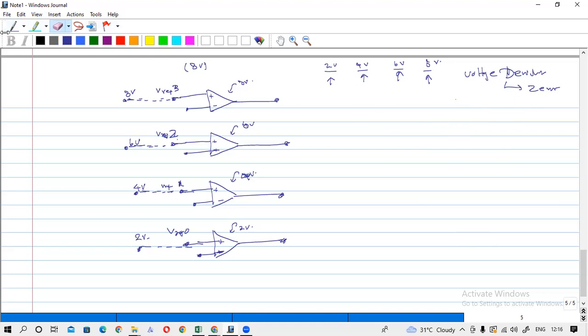Okay, so anyway, what I want to tell you is that to give a certain voltage to this point, you can use the resistive voltage divider, you can use a Zener diode, or you can use voltage regulators. Okay. Are there any other methods? Other methods do not come to my mind, but there may be other methods also. Okay, so here we can use a voltage divider. In many cases we are using the voltage divider here.